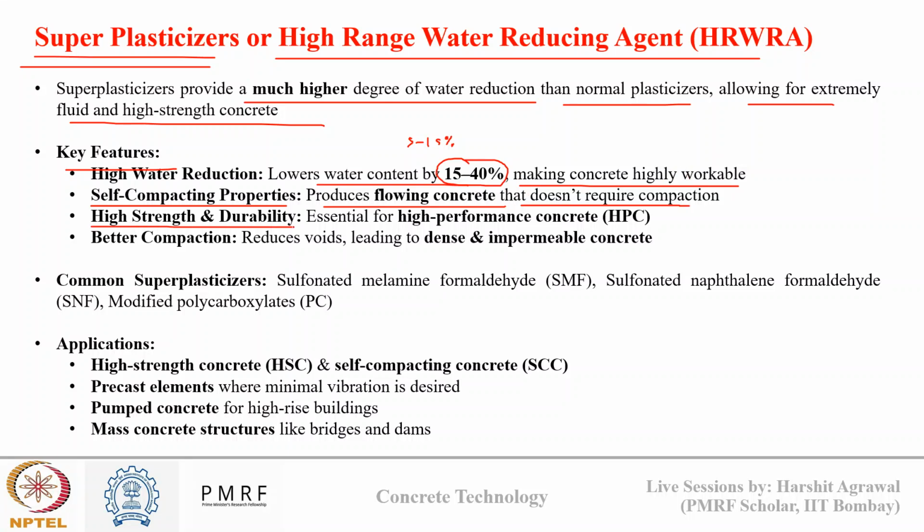They are used in high strength and durability concrete, which are essential for high performance concrete, and they promote better compaction in concrete. By making concrete workable, they reduce the air voids inside the concrete while pouring it inside the formwork, which leads to the creation of dense and impermeable concrete.